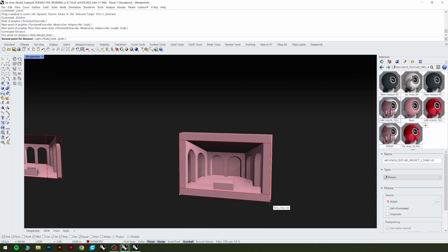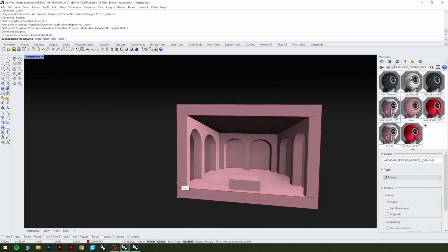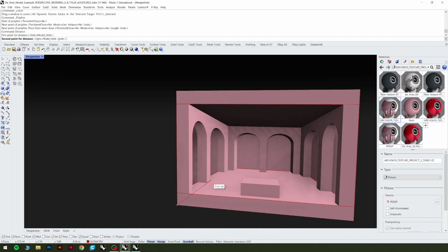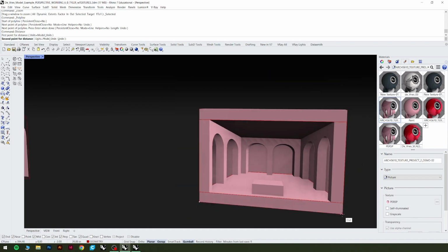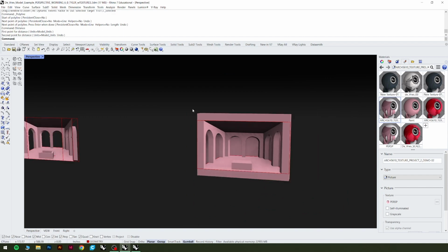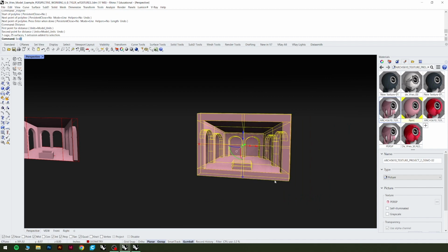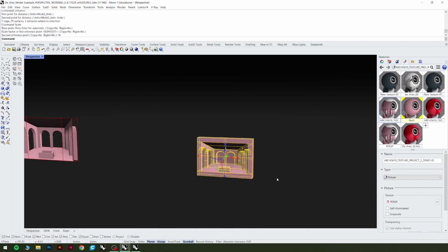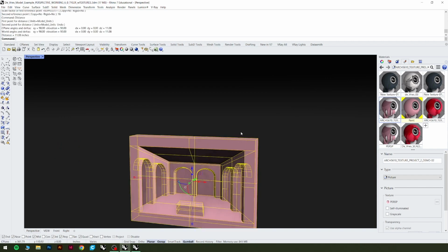But then you just have to consider that if this is supposed to be 16 inches, am I going to add 2 inches and deliver something that's now 18? If I add an inch here, all of a sudden I'm bringing in an 18-inch wide model. You probably don't want to do that. I would make this 1/2 inch at most, and then scale it accordingly. As I have it modeled, it's 26 inches, which is pretty big. But you can get to this point and then scale the whole thing with the scale command. Go to 16, there we go, and then you check what that distance is vertically, and then maybe you'd move the top or bottom faces in.